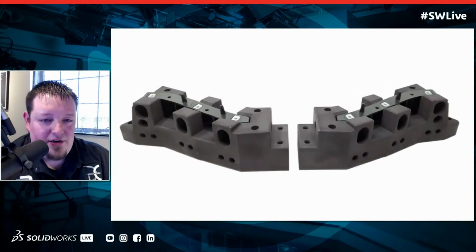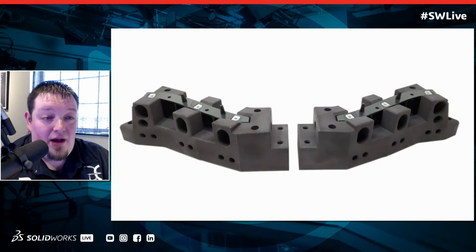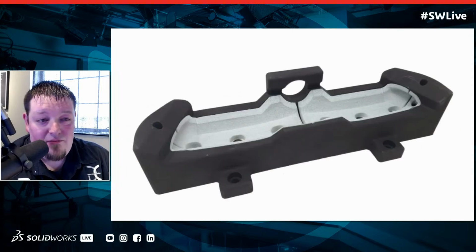Yeah, so the parts that you see right here are interior automotive parts. Not interior to the car, but interior to the body of the car. You'll never see them, so there's no Class A finish requirements. But let's say in the next slide we're going to look at, maybe you're assembling a chrome door handle. Well, this nylon would scratch chrome. It would scratch paint. It would scratch mold and color.